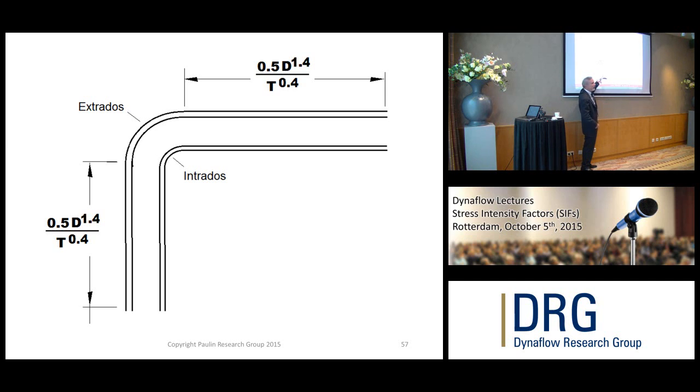So what happens in general in piping systems, you don't have these lengths, because as the D over T gets bigger, this number gets really big. So you don't have these lengths, so you don't have the I's and the K's. You've got a different K factor for each bend, which Caesar really doesn't give you much of today. And you've got a bigger bend than you have attached pipe, because the bends are made thicker.